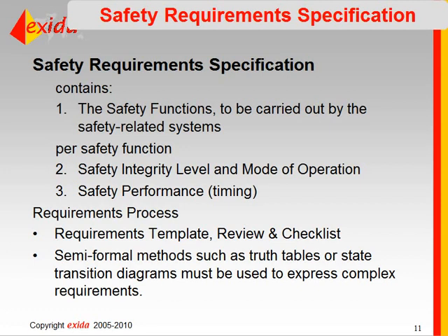And then the mode of operation is also defined in the safety requirements. Are there different modes that apply to that function? Does the product work differently, like during startup, for example, or is there a sequencing or a learning phase, etc.? The safety performance needs to be defined. So if there's a function that has to do something like detect a condition and shut down, you need to define how quickly it must do that.